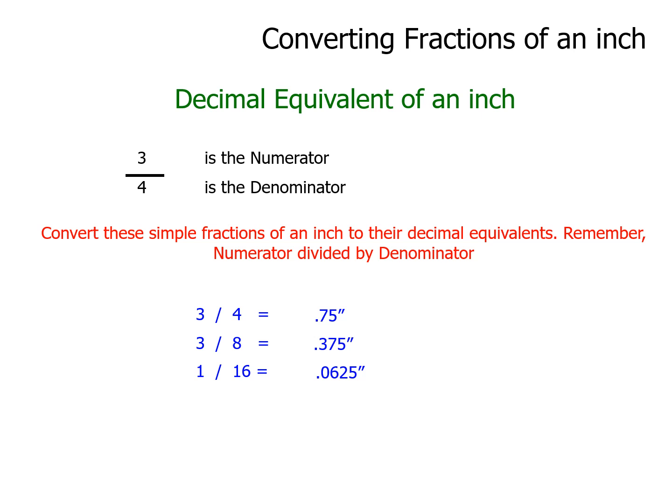A lot of times in math, especially in estimating, the more you do something, the more you guesstimate things. We don't accurately estimate all the time when estimating. We guesstimate. We'll look at a circular shape and square it up. The reason is I don't want to run short on concrete when I order it, so I always want to order more than I need, so I end up rounding up.